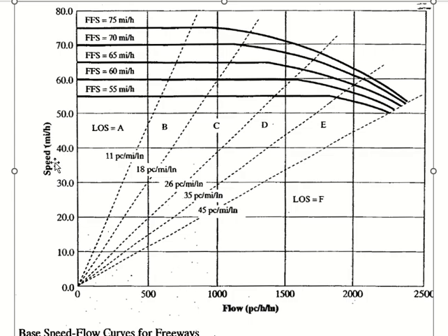Density is flow upon speed. If you take the inverse, 11 is density, and density equals flow upon speed. So if you take the inverse of this value, it becomes the slope of this graph, because the inverse will be speed upon flow. So 11 is density, density equals flow upon speed, and the inverse of that will be speed upon flow, which will become the slope.